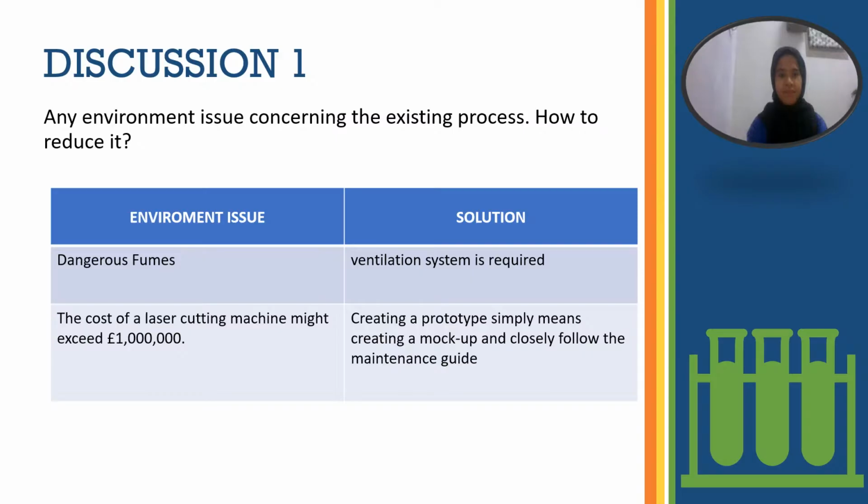For discussion 1, an environmental issue that happens in laser cut is dangerous thermal. The thermal cutting procedure causes the material to melt, so the result produces gas and potentially toxic odor. For the solution, a ventilation system is a requirement, although expensive.